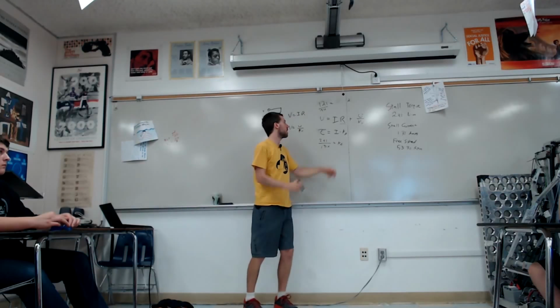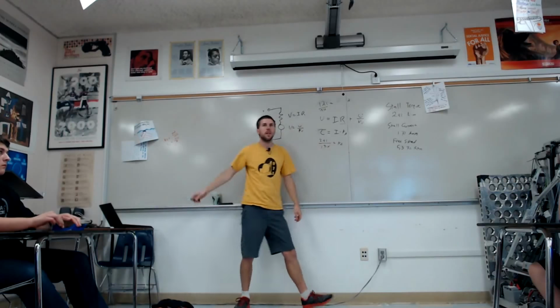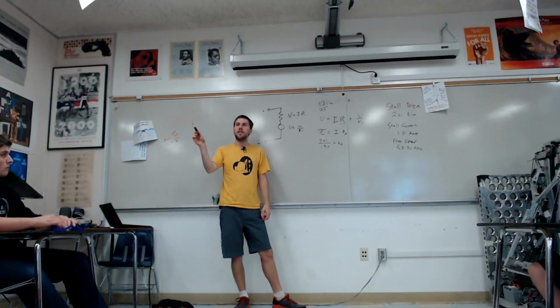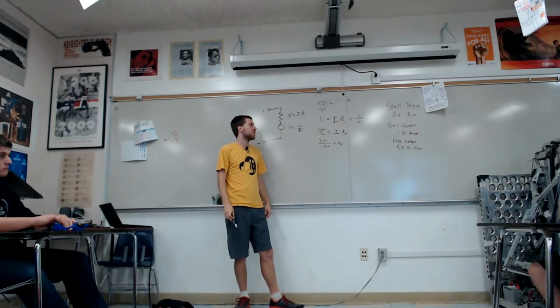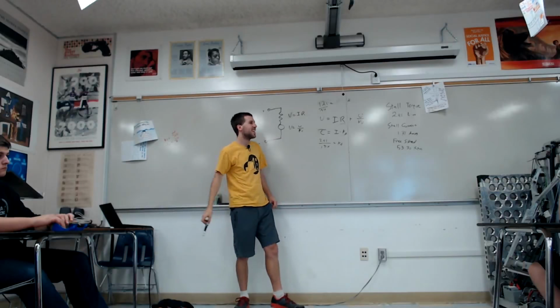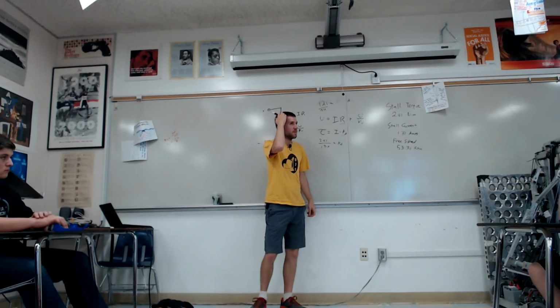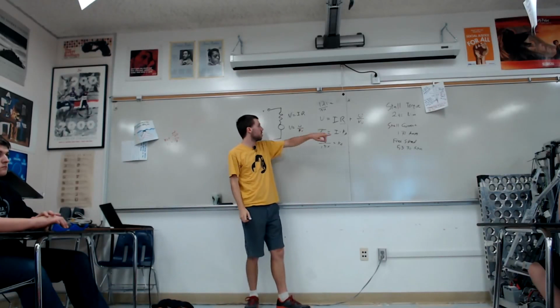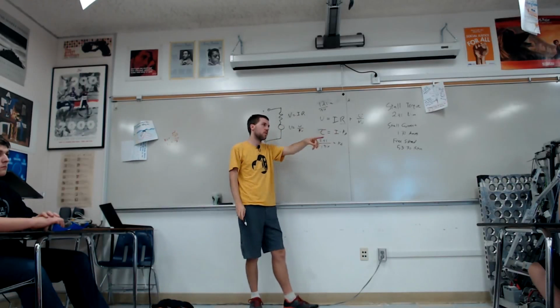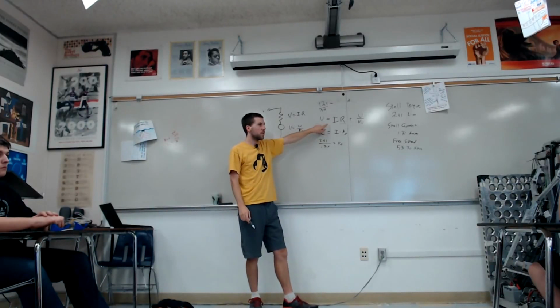Getting close, then we got one left. Anyone see how to get KV? You want to use the free speed. Use your free speed and then put it to the right. So for our free speed, our torque is 0, which implies that the current would also be 0.